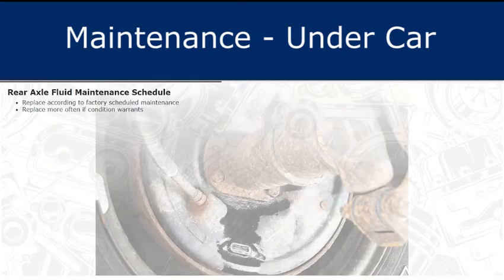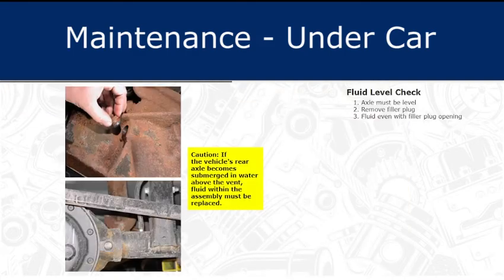Replace fluid according to the factory maintenance schedule. If conditions warrant, it may be necessary to accelerate this schedule. When checking the fluid level, verify that the axle is level before removing the filler plug. The fluid should be even with the filler plug opening. Caution: if the vehicle's rear axle becomes submerged in water above the vent, fluid within the assembly must be replaced.